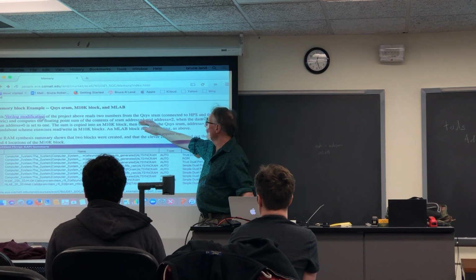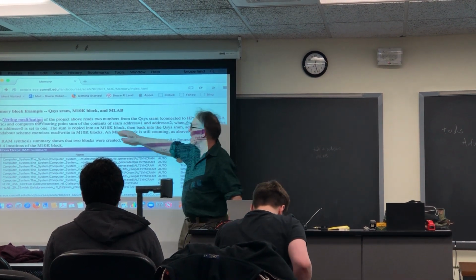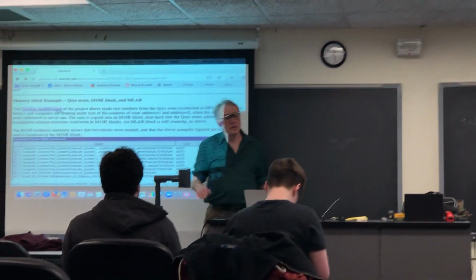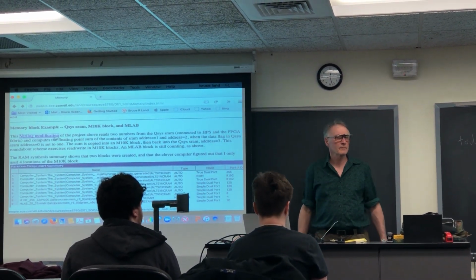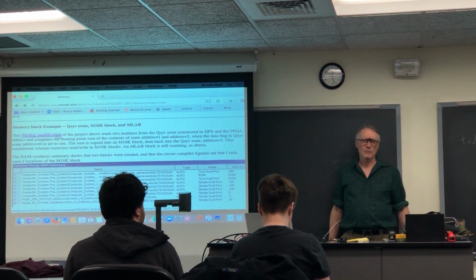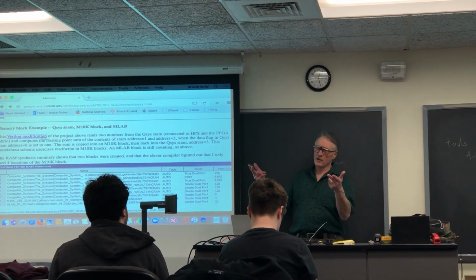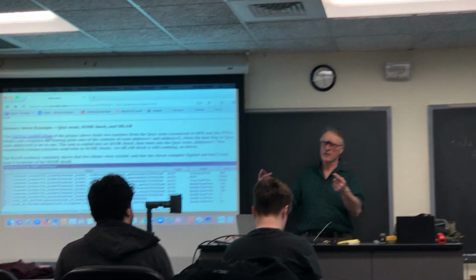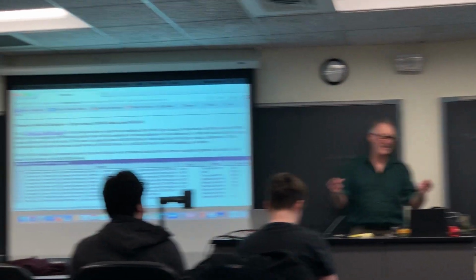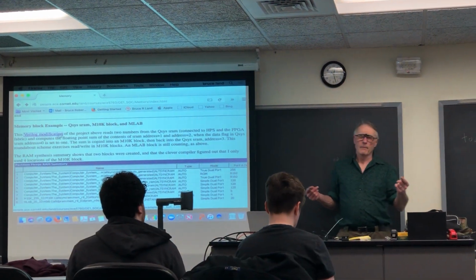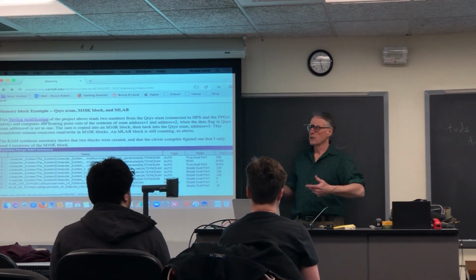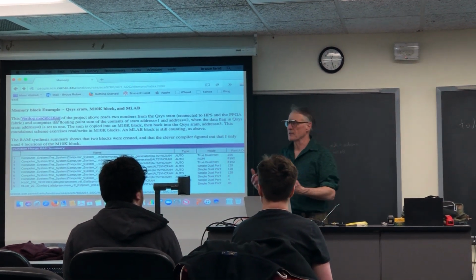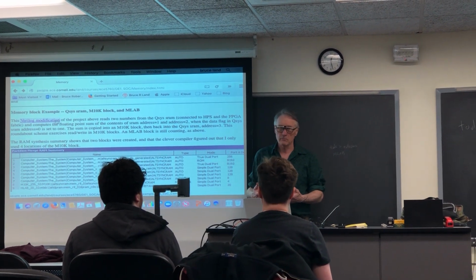And you have about 400 blocks of M10K, each one of which is 10 kilobits. So the trade-off is denser memory, but it's serial. Whenever you use one M10K block, you would expect to access it with a serial state machine.